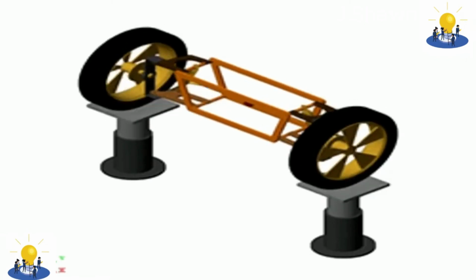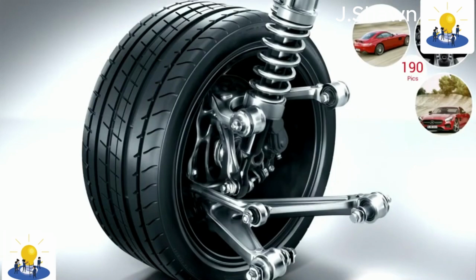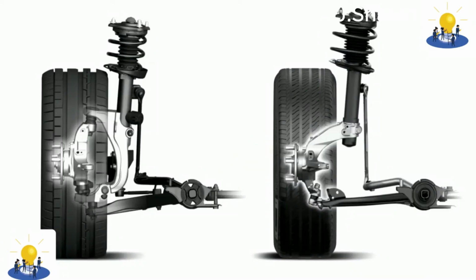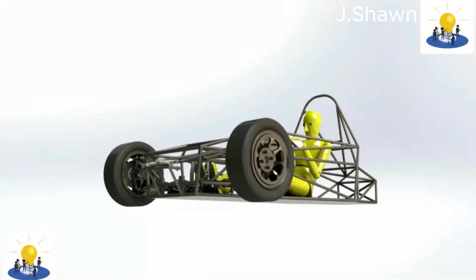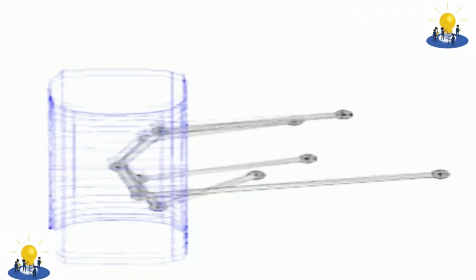The double wishbone suspension can also be referred to as double A-arms, though the arms themselves can be A-shaped, L-shaped, or even a single bar linkage. A single wishbone or A-arm can also be used in various other suspension types, such as variations of the McPherson strut. The upper arm is usually shorter to induce negative camber as the suspension jounces, rises, and often this arrangement is titled an SLA, or short long arm suspension.